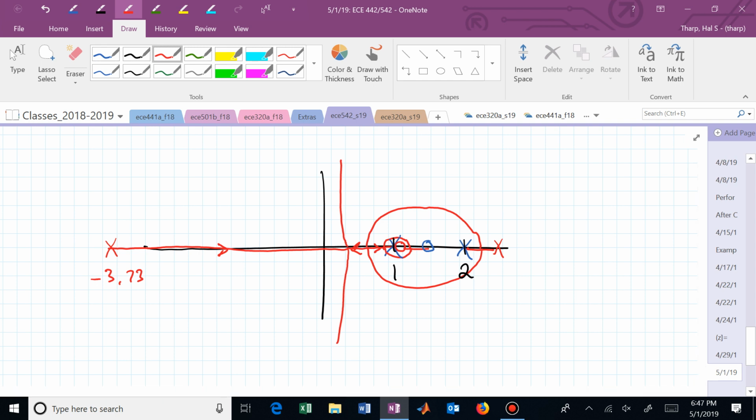So actually we have 4 branches simultaneously inside the unit circle, and it is stabilized, but we had to put a controller pole at 2.5, another controller pole way over here at minus 3.7, both of those outside the unit circle, 2 unstable controller poles, and we put a controller 0 outside the unit circle, but voila, we adjust the gain just right, and we can end up inside the unit circle.